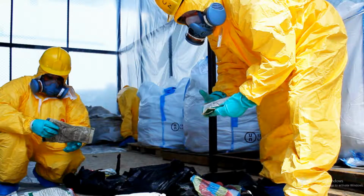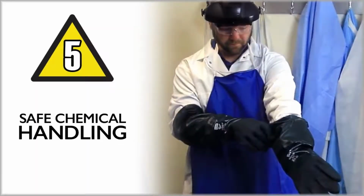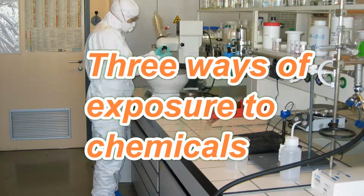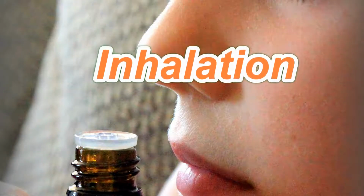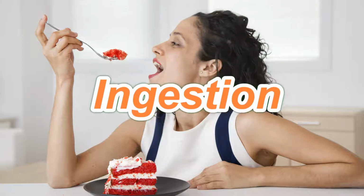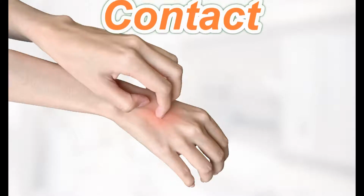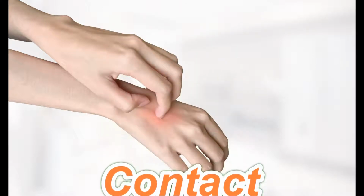Working with chemicals is a hazardous activity, and chemicals can harm or injure workers in different ways. There are three main ways of exposure to chemicals during working. Out of these three, inhalation is the most dangerous way of exposure. With ingestion and contact, the workers have more control and they can refrain from eating or swallowing, and stay away from chemicals to prevent contact with skin.